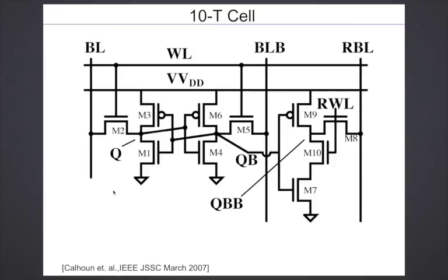So when I go to sub-threshold and I go down to 8 cells or 4 cells per column, it's just not going to work. The area overhead is just going to be enormous. So that is a problem. Here what they are saying is, let us try to keep the area small by increasing the number of cells in a column. Let's go back to the old way of 64 cells per column or 128 cells per column and so on. And can we address the problem of the off leakage from the cells which are not connected? So that is why they have this structure.